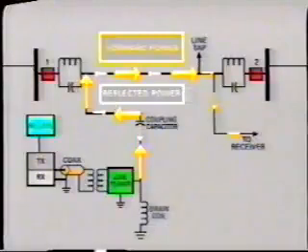Reflection of a signal can be explained by a simple and familiar analogy. When you shine a flashlight through a glass window, most of the energy passes through the glass. Some, however, is reflected back to you. The reason for this is that the glass and the air have very different optical characteristics. And when the light beam leaves the air and enters the glass, some reflection occurs. In our communications circuit, reflection will occur at any point where a discontinuity in impedance takes place. For example, where a second line is tapped into the transmission line.